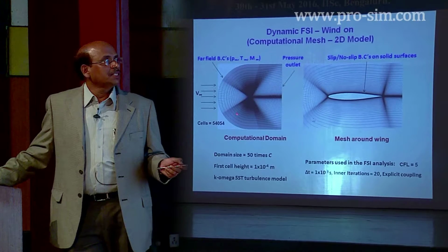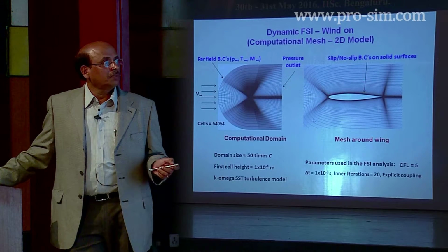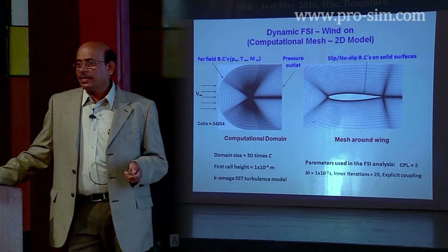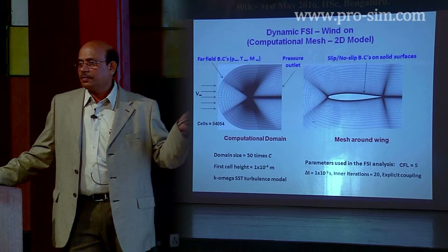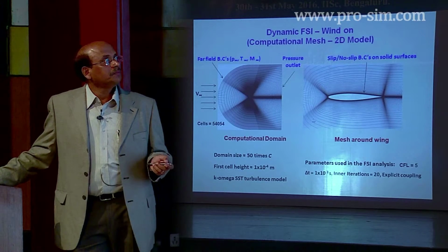Okay. So this is the CFD mesh that we have used for solving the problem. And coming to the structure, there is no finite element mesh required here because it is a simple 2 degree of freedom airfoil that we are considering.